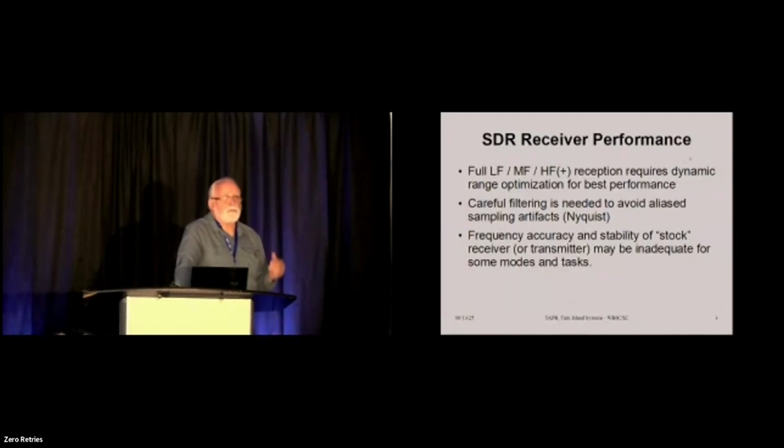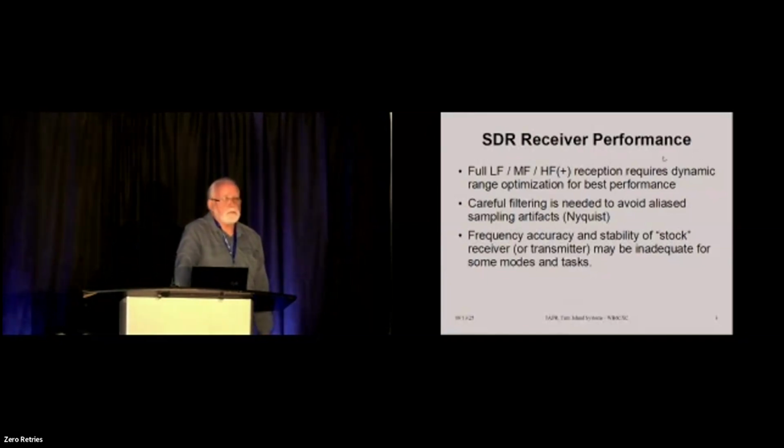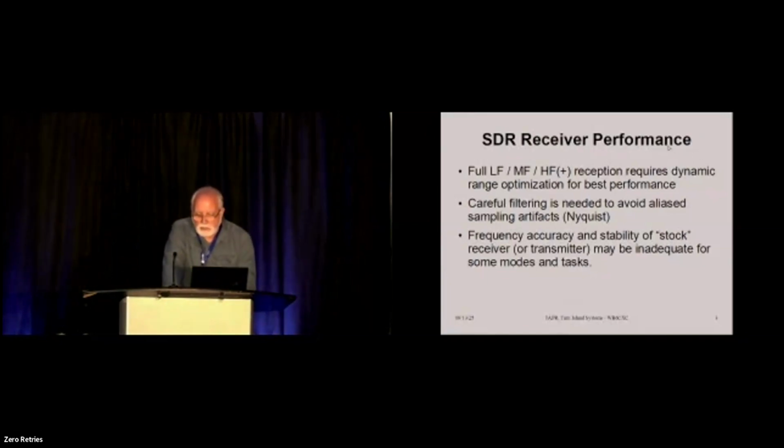By measuring the frequency, we know the transmit frequency, and this is down to millihertz or in many cases microhertz. And if the receiver has an accurate frequency measurement, we can measure the Doppler shift, and it can be many hertz of Doppler shift. And the better we can measure that, the better our data.